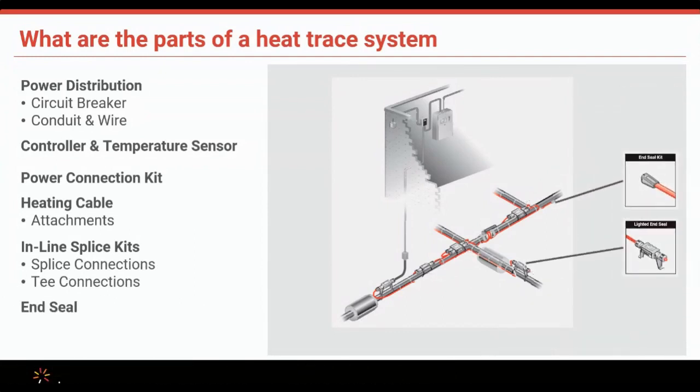And then finally, wherever you're ending your pipe, you want to have a termination kit that is approved with the product. I have gone out to the field and I have found I get to the end of the cable and it is electric tape that is tying this section down. That's not an appropriate or approved way of doing it. So we always need to have end seals.